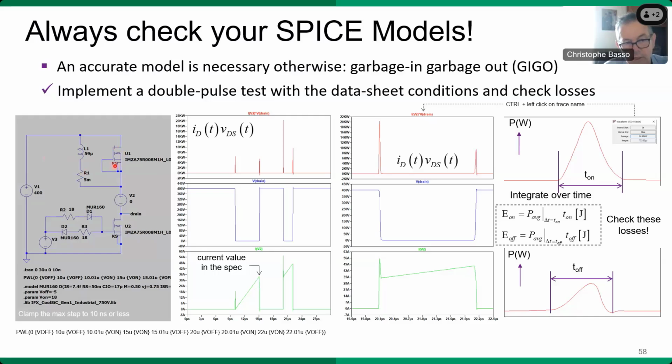And also the inductances, if the SPICE model is well modeled, they are included inside the model, but the bonding inductances and this kind of thing. And this truly complicates, first of all, the simulation time, but also the parameter extraction that very few people do. So be very careful when you consider switching losses with a SPICE simulation. If the power distribution network is not well characterized, it may give you an idea of what the total losses of your transistor will be, but it cannot replace the measurement on the bench and in the lab, of course.